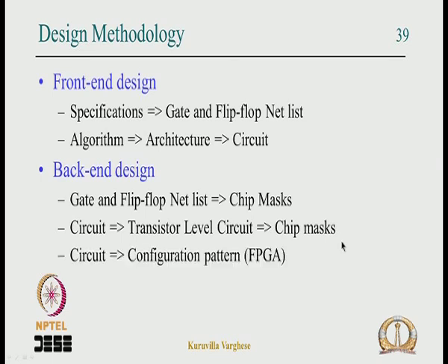But if you take the FPGA, we do not go for this step. The FPGA already has the logic circuit built in as logic resources with the wires laid out with switches in between. So you literally go in one step from the logic circuit to configuring the FPGA.